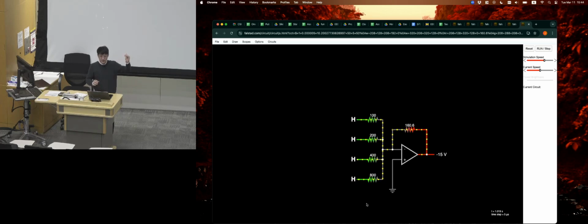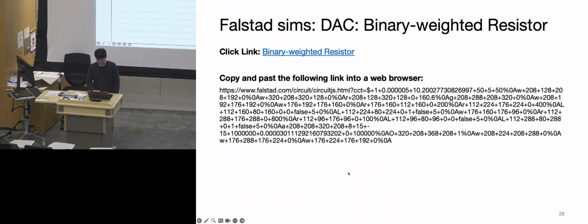So all of these different configurations using the same voltage divider idea are an effort to reduce the amount of hardware being used. But there is no strict good or bad between them; it just depends on the trade-off you're making, such as cost constraints versus space constraints. The underlying idea is the same within these: use different values of resistors, divide the reference value into different steps, and then selectively turn on which step is connected to your V out, and that's your output value at that cycle. Does it make sense so far? Okay. Cool.